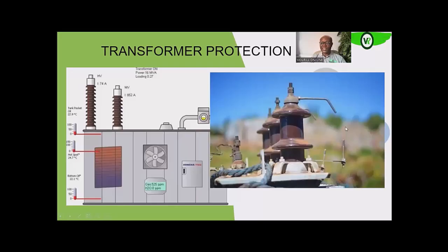The dielectric strength of the air between the contacts of the arcing horn is strong enough to withstand the voltage forcing charges or current to flow through to ground. So in normal condition, there won't be any flow, because the dielectric strength of the air between these two is strong enough to prevent such flow.